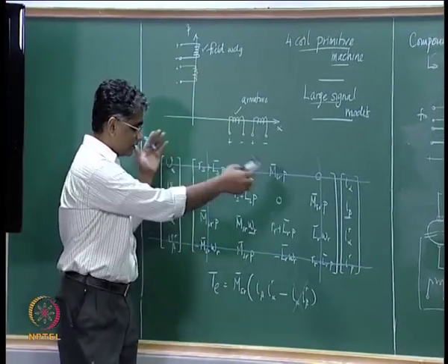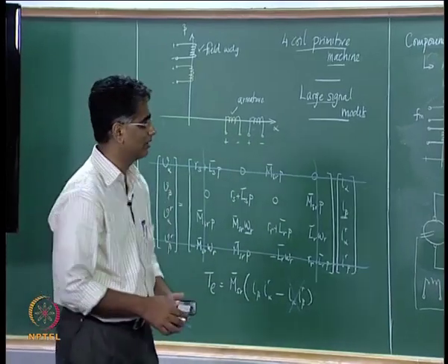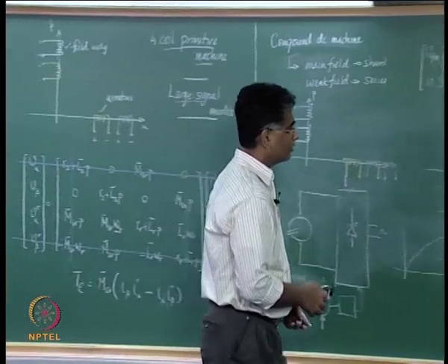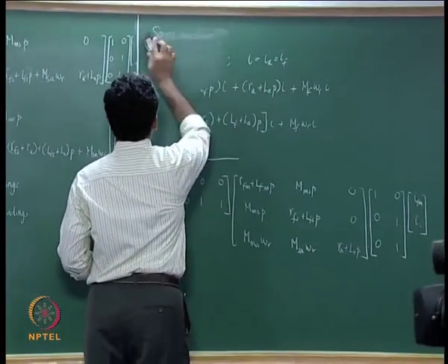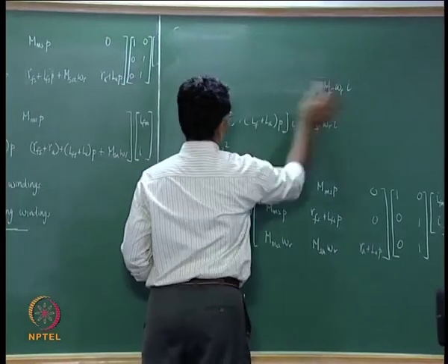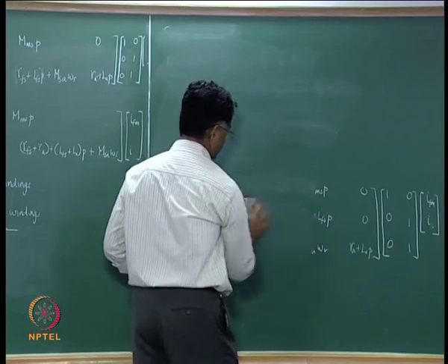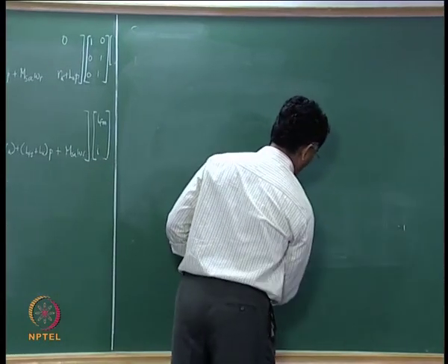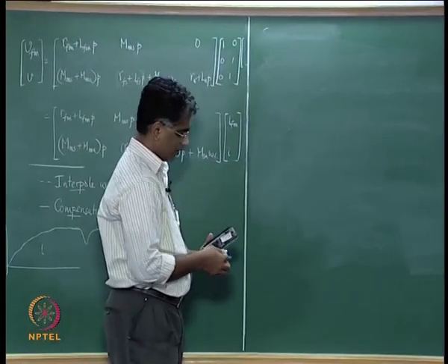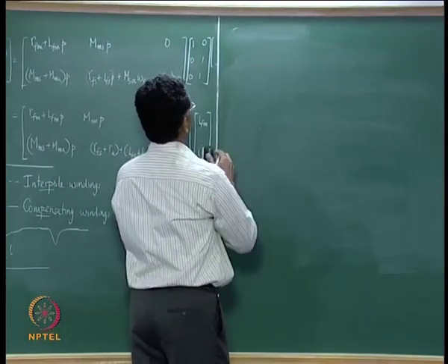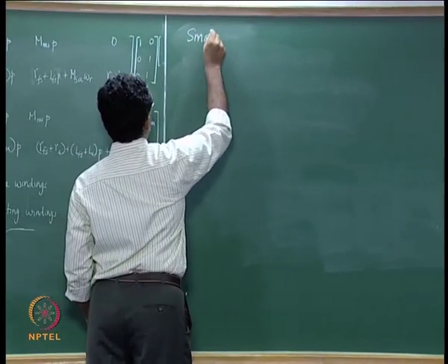But if you consider all these things put together, then yes, it becomes a nonlinear system. So, if you have a nonlinear system, in order to do control on this, it is usual to consider a linearized model, and what we do to get a linearized model is to apply the method of small perturbations.